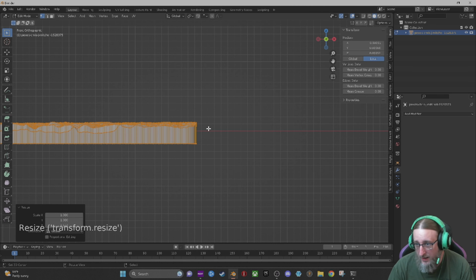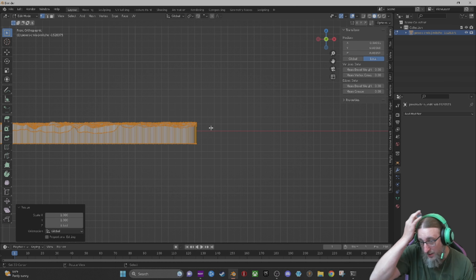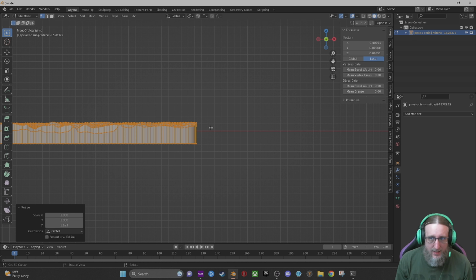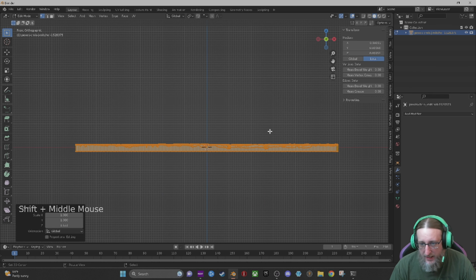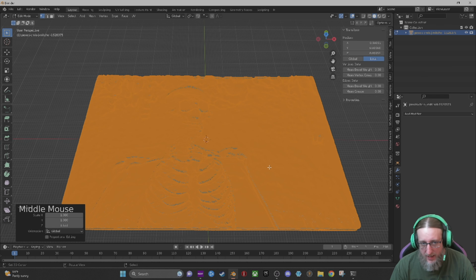You can go thicker. Like I said, some people like to go a lot thicker. The problem I have is that the thicker you make it, the less detail you get, because less light comes through. If I have a super thick plastic and I put a light up to the back of it, you might not see any light peeking through. So if there's a tree that has a couple sections that are just slightly lighter than other sections, you won't be able to tell that difference if it's too thick. So I generally try to keep it as thin as I can to get better detail out of the pictures themselves. But 3 millimeters thick is perfectly fine, and it also saves you on plastic.